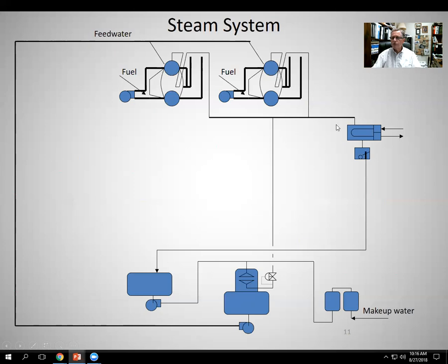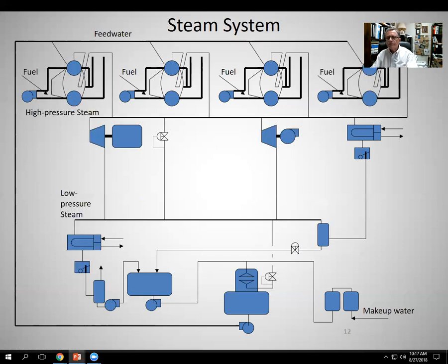I think that covers it. This is the steam line with a flow control valve that goes to the deaerator, which is, another term for that is an open feed water heater. And it's open in that it doesn't show it here, but there's a little vent on this that vents a little bit of steam and the oxygen and non-condensable gases to the atmosphere.